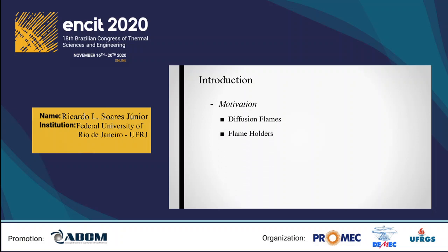Most studies of diffusion flames in the presence of irregular walls are related to flame holders, for which the solid wall is located downstream of the flame. And in the flame holders, flame-wall interaction, for example, is a field of combustion that has not been investigated yet with sufficient care. So the objective of the present work is to evaluate the interaction of the wall irregularity and the reactive flow. A parametric study is conducted to evaluate the effects on the recirculation zones and the flame shape of the position and the size of the irregularity, of buoyancy, and of the Reynolds number of the fluid flow.